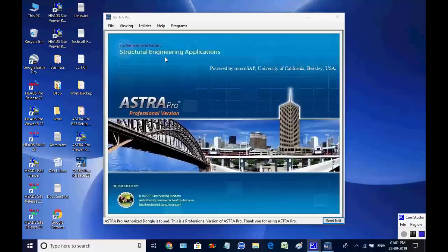In this session we shall see the modeling of a block-type machine foundation by using 3D solid brick elements and the dynamic analysis of the block model for eigenvalue analysis. We shall analyze two models. In the first model we shall see the analysis results for displacements, and in the second model we shall increase the size of the block model by resizing with application of factors to increase the mass of the model and see the reduction in displacements.